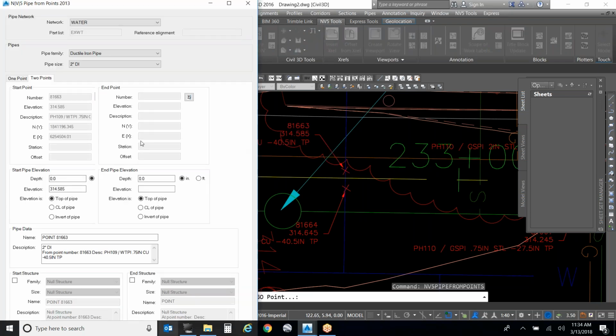So the elevation that it picks up is the surface point, the point of the shot itself, right? When we go and gather this survey data, what's our data? Measuring down, physical measurement. The point itself, the survey shot, is at the top of asphalt. In this case, they are not shooting the top of pipe. Do they ever? Yes, they do. Which comes into play on the next step as well.